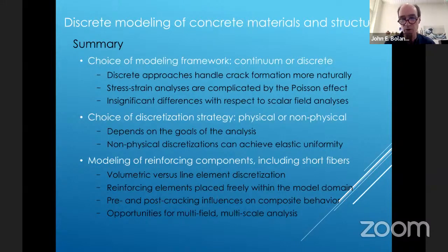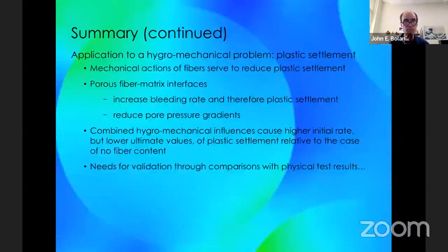The line element approach is computationally much better in terms of cost. We can put these elements freely within the domain. We can model the pre and post cracking influences on composite behavior. And as you've seen through the example I showed, we can use them for multi-field, multi-scale analysis.